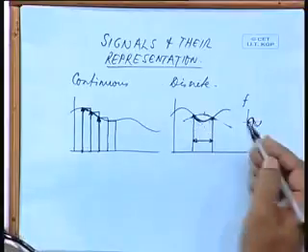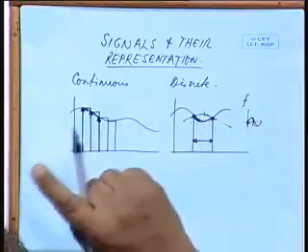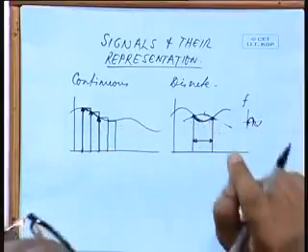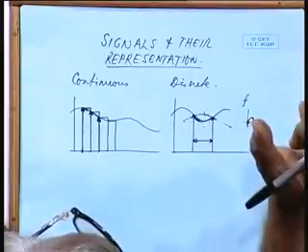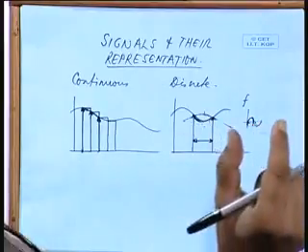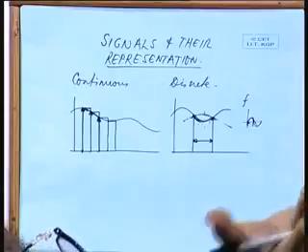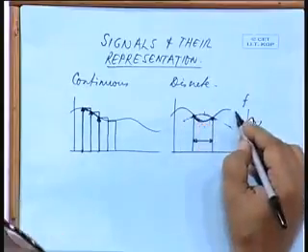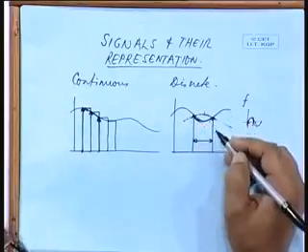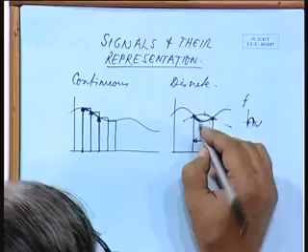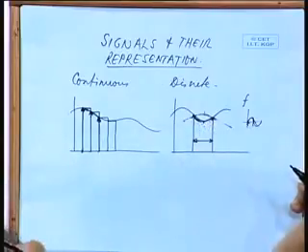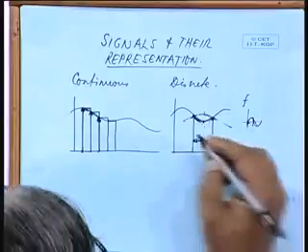So, the maximum frequency that is present, that means the maximum number of changes that may occur in the original signal, twice that frequency, if I sample the original signal at that frequency, then only I will be able to just recover this point. Okay.